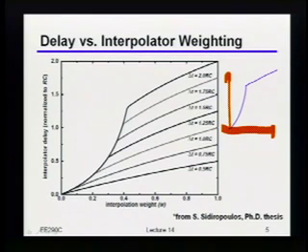And by the way, the range you're covering is obviously from here to here over a certain code space. So if it was linear, oh yeah, go ahead. Well, the resolution is kind of low in the first part and then too high in the second part. There we go, exactly. So the problem here is that the worst case step size you're getting is crappy, right? Because if I had a perfectly linear thing, it would have just looked like that, right? So in this region right there, I have way too big of a step, so I have crappy resolution. And in that region right there, of course, I have these really, really small steps, right?